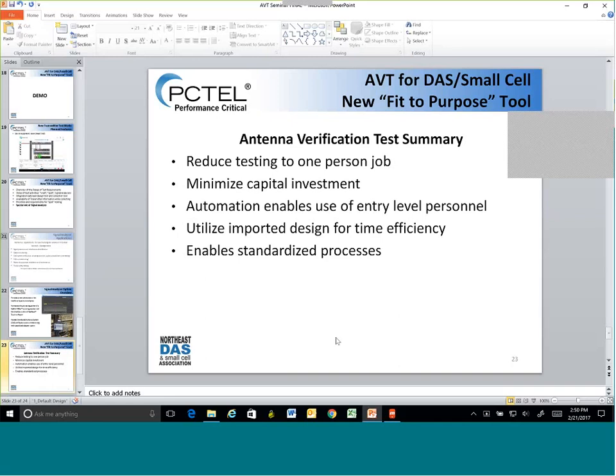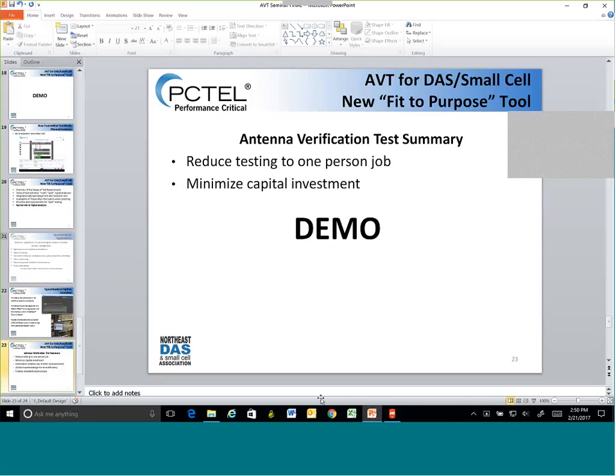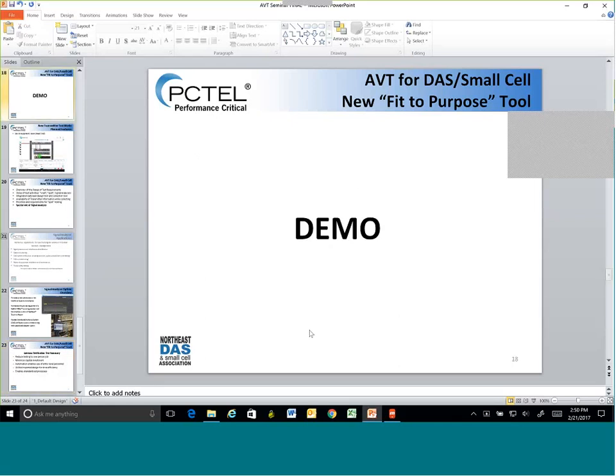Okay, great. Another question that we had: if you wait until the DAS signal sources are installed and operational, LTE, CDMA, etc., construction is long done on the DAS. Isn't it better to find these issues early in the process while construction is still underway, e.g. using CW test gear? Yep, absolutely.